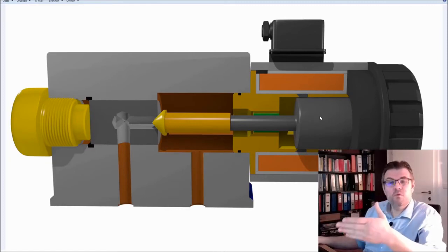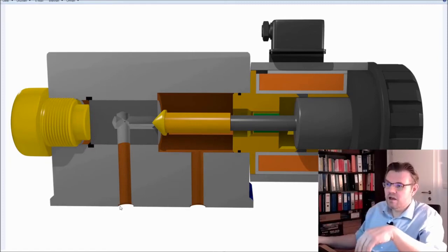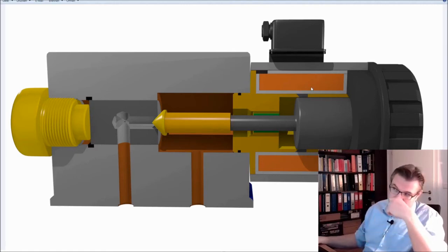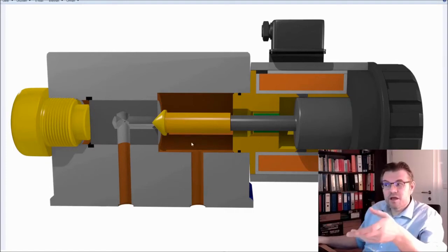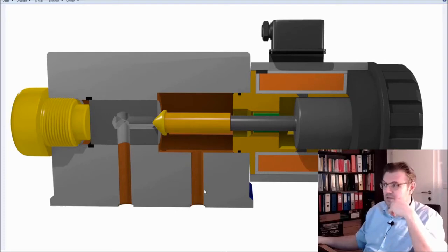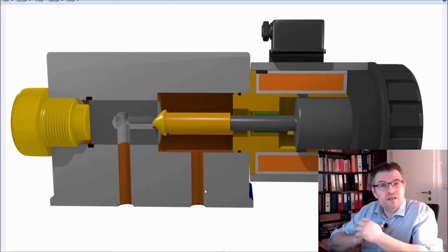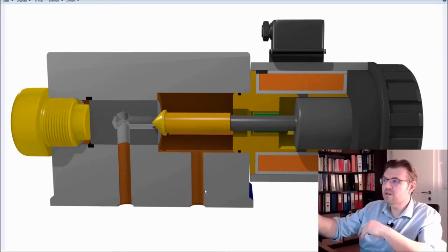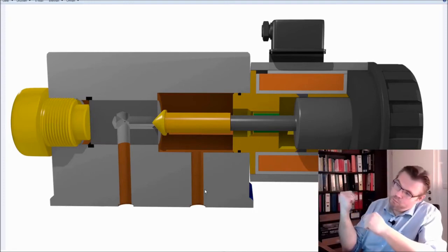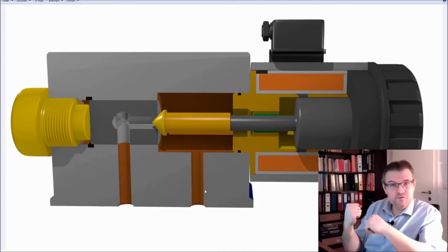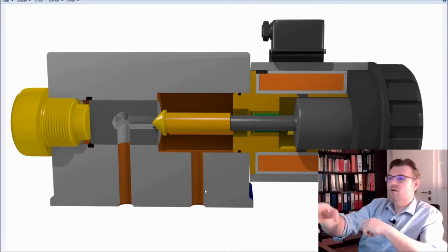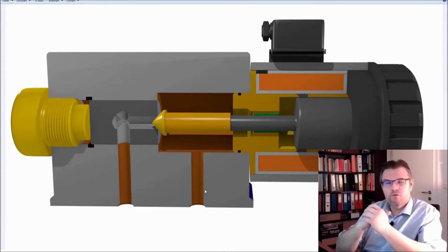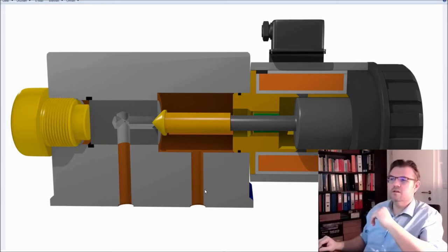So this is a proportional valve. If I have high current here, I need high pressure, then I get high pressure back. If I have low current here, I need a lower pressure, and I get a lower pressure out. It's a proportional valve. Okay? This is how such things look like. So there is a coil. The coil is producing a magnetic field. The magnetic field is pulling in an armature. The armature is acting inside the valve somehow with a force. It might look like this.